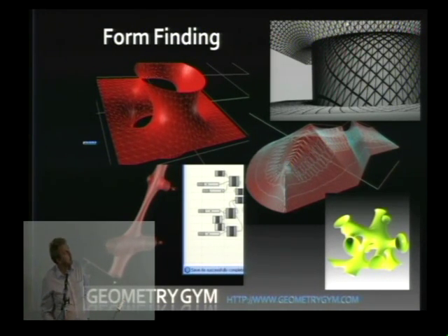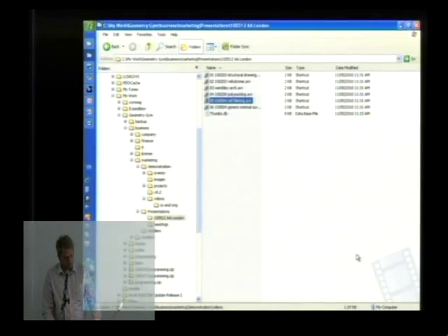But effectively letting the mesh relax itself so that you get those nice sweeping curves, which gives quite a stunning shape. It's for finding things like Costa's minimum surface or a more generic mesh relaxation surface, which I've seen in a couple of atrium installations. And there was some nice work by a young student in Germany who, I originally basically wrote the routine thinking, that's a bad example of a tent or membrane type roof, but he used it for finding some quite nice organic shapes, so it can do some pretty powerful stuff.